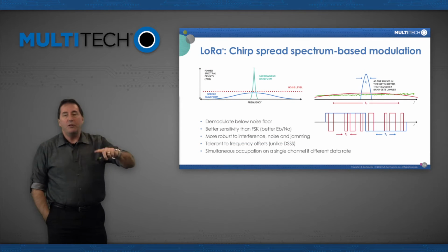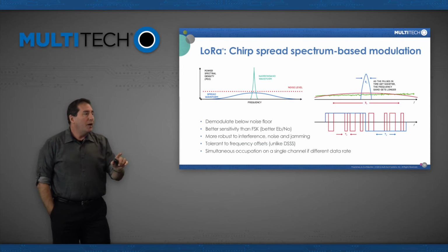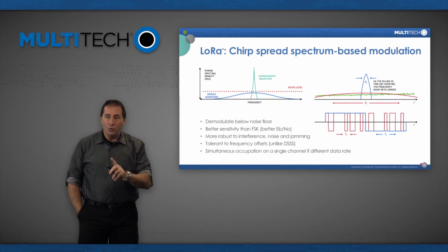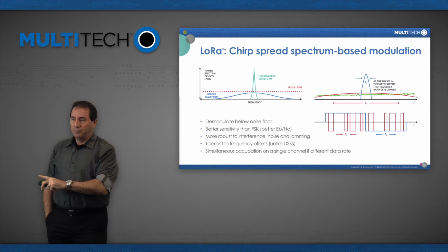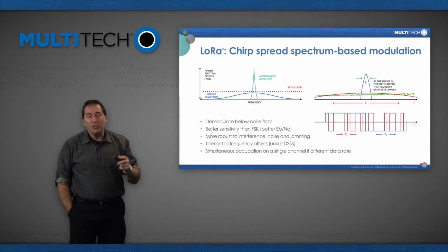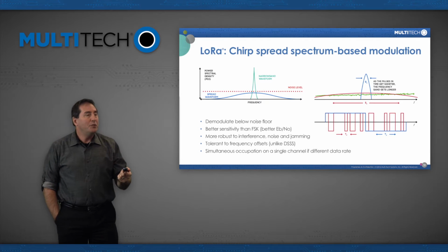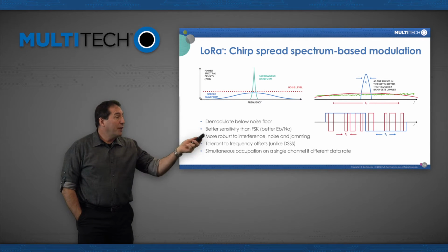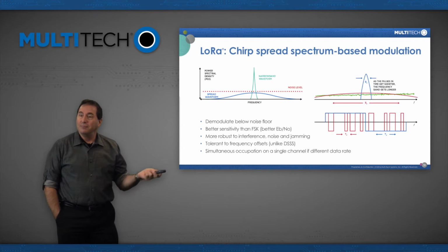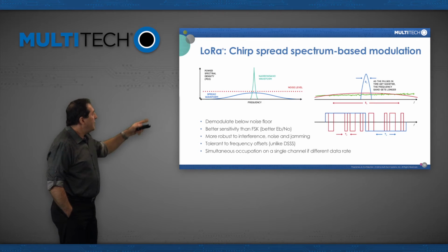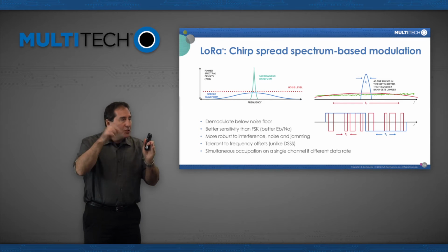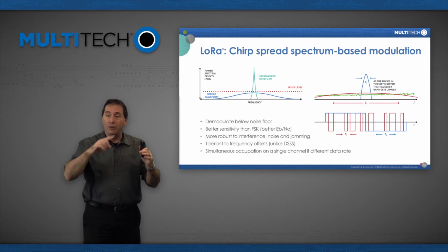So at the lowest level, let's start with the radio. LoRa is actually a fairly old technology. In fact, it is so old that all the original patents have expired. It kind of came out of the military and intelligence services, where they wanted to be able to communicate over a long range, reliably, and not be listened into, right? So what did they come up with? They came up with a signal called Chirp. Chirp is just a way of modulating a signal in bursts without having a carrier wave.